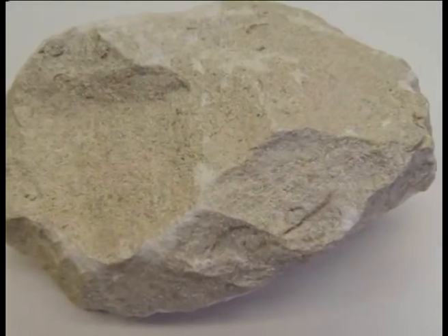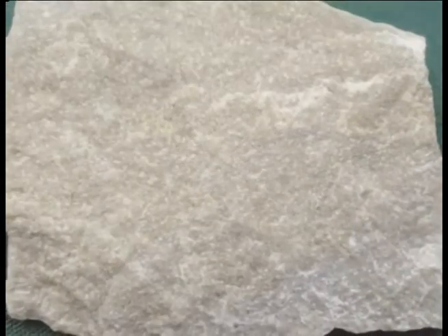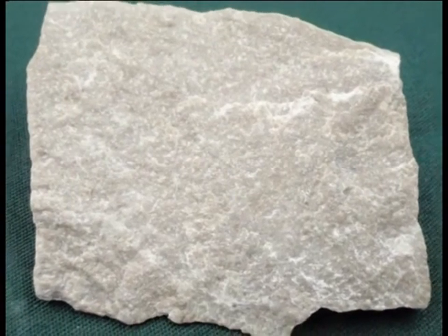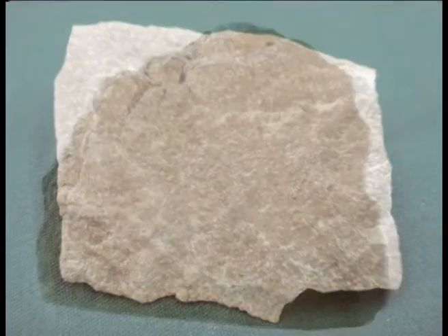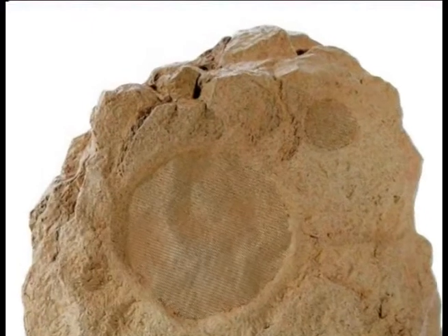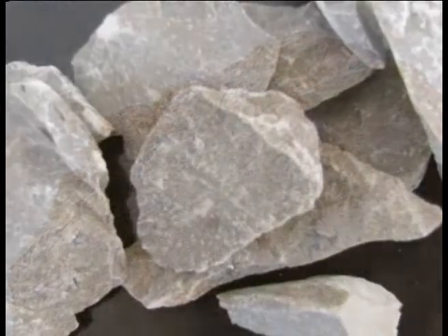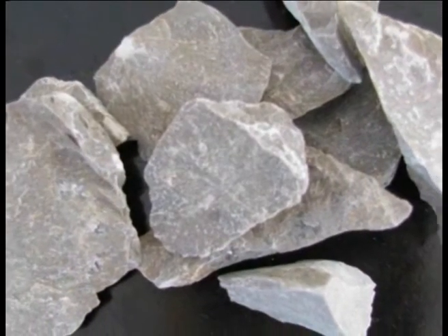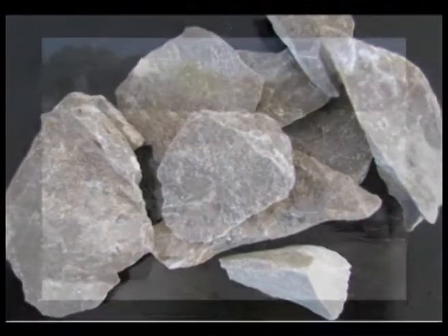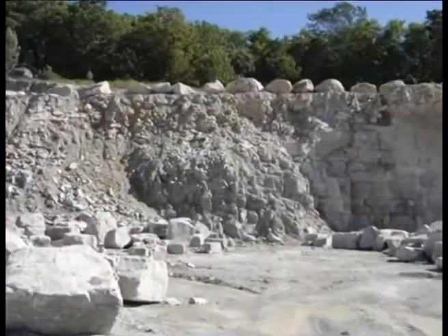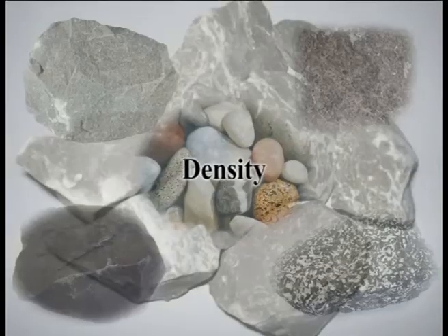Selection of such highly porous varieties of these stones for use in building constructions, especially in most situations, would be greatly objectionable. Presence of water within the pores not only decreases the strength of the rock, but also makes the stones very vulnerable to frost action in cold, humid climates.